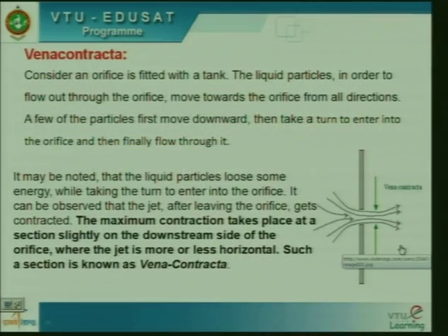At that intersection, on one side there is erosion and on the other side there is what is known as deposition. You are going to study this in irrigation engineering. For now, please remember that the momentum of the flowing fluid cannot be changed abruptly. With that concept, let us see when this Vena Contracta is going to form.